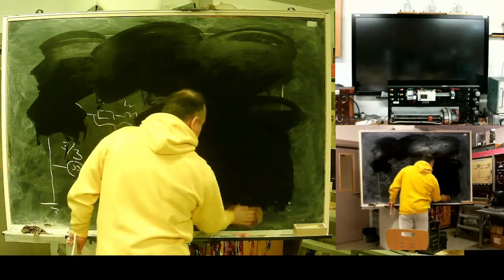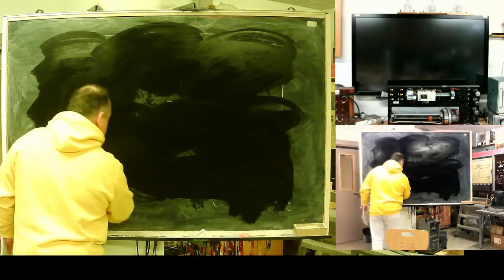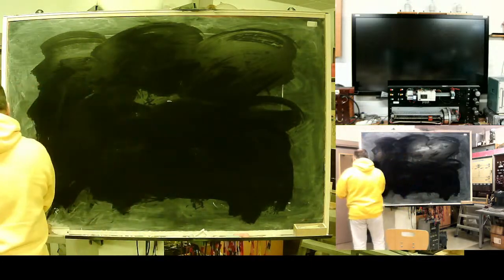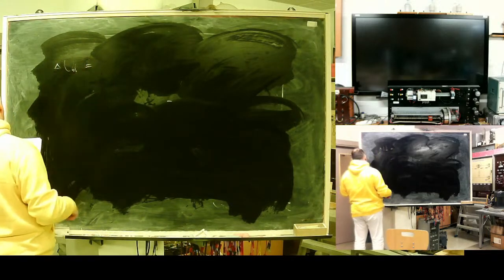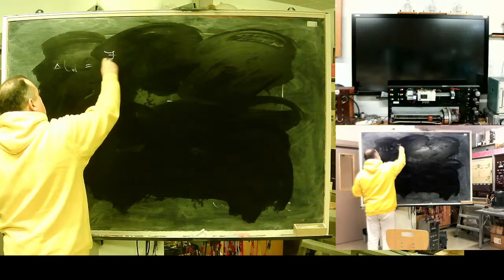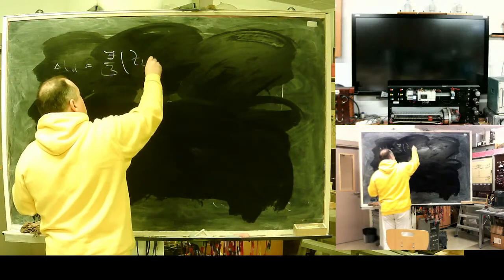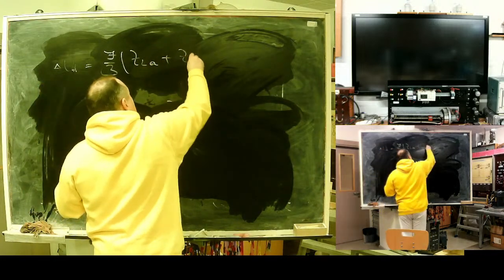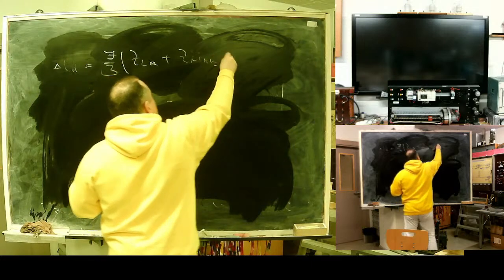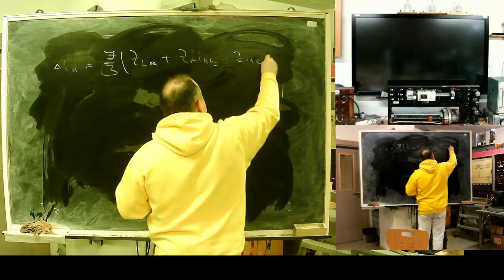Okay, I wrote it. What will be my system? For A phase, the voltage drop will be 1/3 of the current times self-resistance plus mutual AB plus mutual CA.